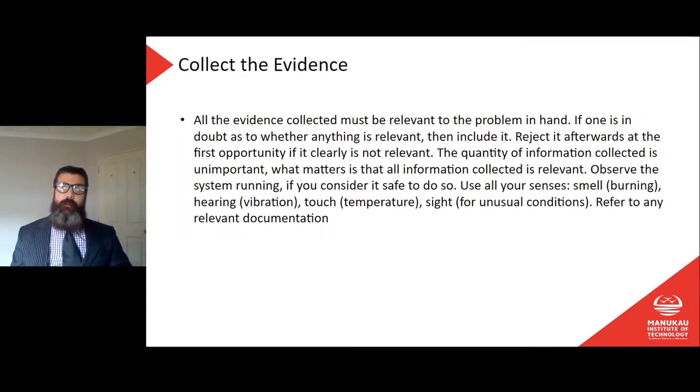If you walk into somewhere and you find that all the power points and all the lights in one room aren't working, well, now I probably want to go back to the switchboard, because that certainly sounds like I have a circuit breaker that's controlling all the lights and power in that room, and that's flipped off for whatever reason. I don't want to start pulling apart every power point in that room and every light in that room to see what's happening behind there. That doesn't make any sense.